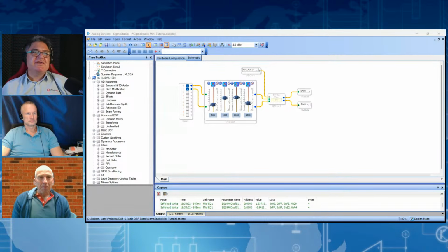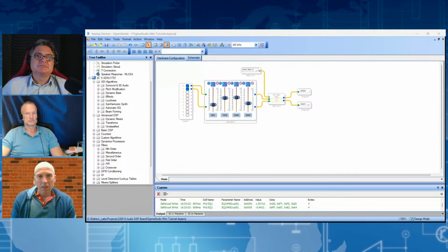Now, how does the ESP32 handle audio independently and yet gain flexibility with the DSP codec? Well, you can use the ESP to generate the audio. There are audio libraries, music libraries for the ESP32. And then you want to hear it, so you just pump it over I2S to the DSP, and the DSP just pumps it through to the output.